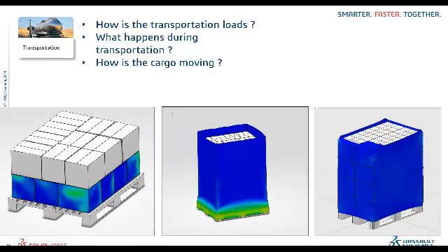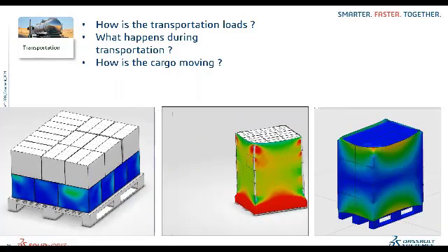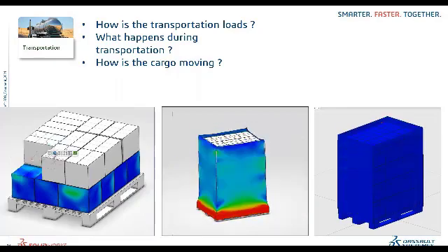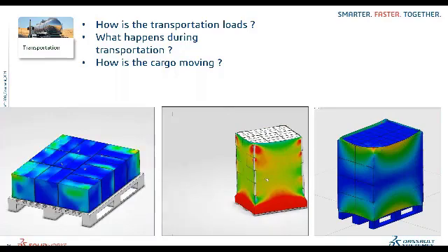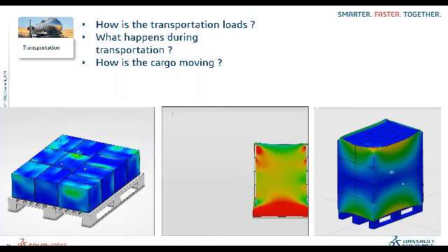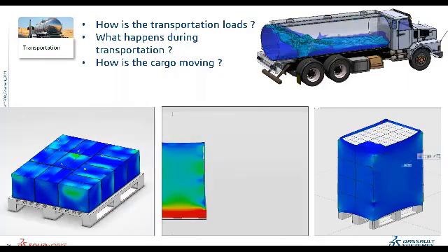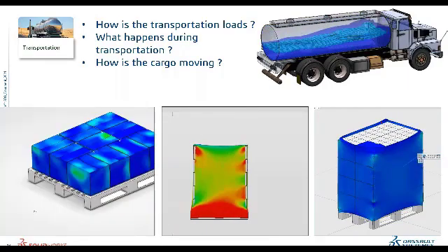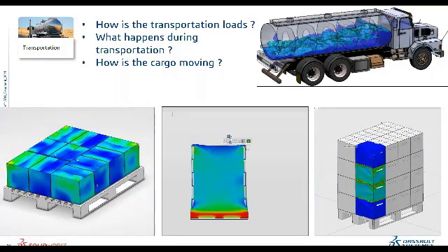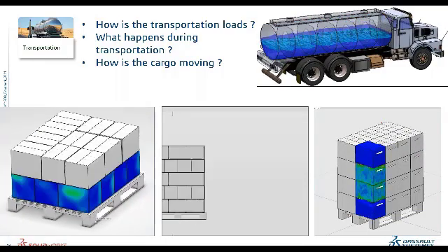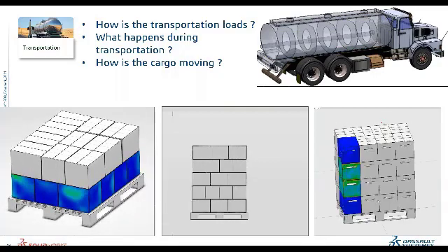And then we have the transportation phenomena, where we will be able to understand the movement when we have the stack configuration. What is the deformation on the bottom stack, where a huge amount of load is applied, and during transportation from one place to another, how exactly things are moving around. There is a concept of the CEL approach and the SPH approach, where we can make use of smooth particle hydrodynamics and see the baffling of the water tanker. With the baffles, how are we able to reduce the sloshing effects?